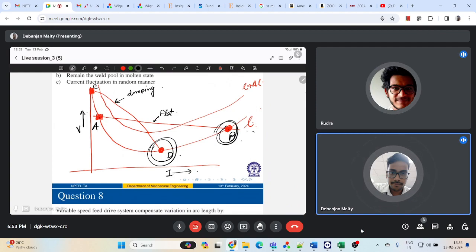However, at the points shown by those solid squares, you will have the opposite phenomena. So any kind of disturbance moves the operating points continuously away from their original location. The changes in the arc current for the two power sources, for a given change in the arc length, are also indicated over there.